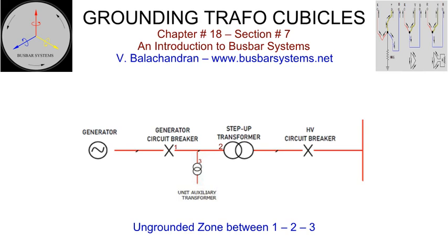If voltage transformers, surge arresters, and surge capacitors are separately installed in a surge protection voltage transformer cubicle on the generator transformer side of the generator circuit breaker, then their capacitances to ground also need to be considered. This combined capacitance of this section and inductance of the transformer coils in parallel will have a specific resonant frequency. The voltage across this tank circuit will be contained by the resistance across it to dissipate the energy. The circuit will still resonate but with a much reduced magnitude of voltage.